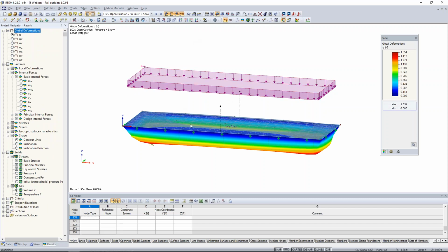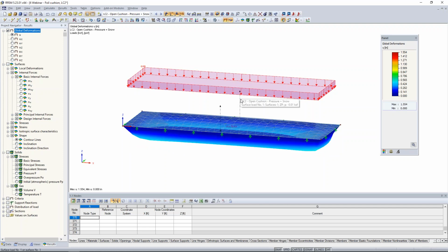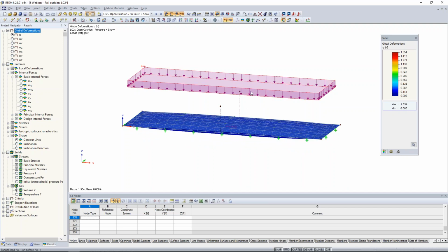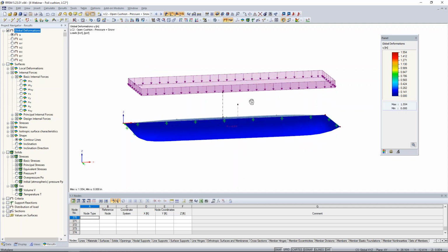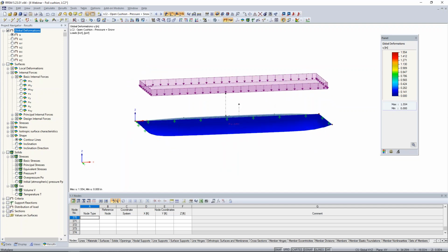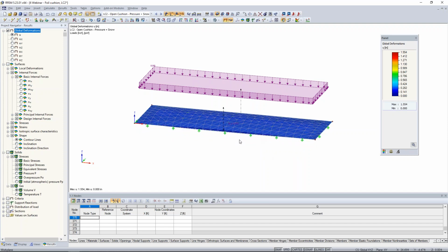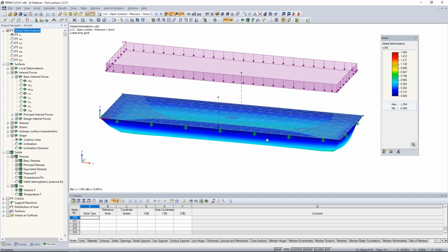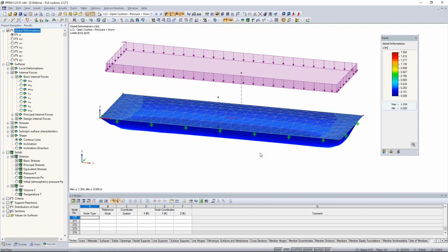What's important to note here is that without this gas solid defined, if we were to apply an area load, this would just be applied to the fabric membrane on top, and it'd probably pass right through the bottom fabric membrane. But as we have it defined now, we have this interior solid with gas properties. So both of these elements are actually deflecting together. Quite powerful, again, in how we can use a gas type solid.